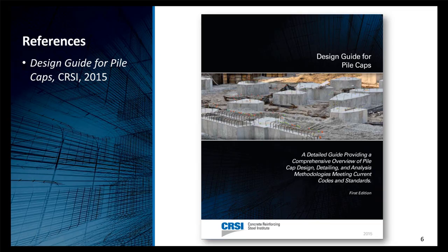One other thing I'd like to preface, and we talked about this last time when we went through the equations, is that in the design guide, they do subtract off the weight of the pile cap for bending and shear. That's certainly permitted to do. That's a weight that's there that counteracts all of the other forces, and you could certainly do that. However, I don't do that in the examples that you see here today. And that's for a couple of reasons.